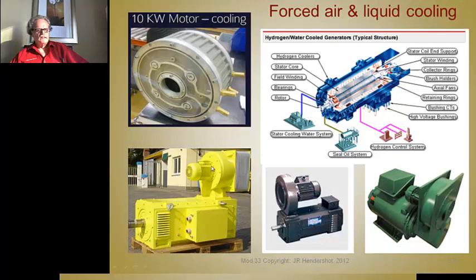Now here's a case of a big high torque density machine with an external blower on it that I don't know if that's blowing or sucking. I believe it's sucking because there's the filter system. You want to filter that air, so this sucks air in there and blows it through the machine, and it vents out both sides of the end bell, so that forces it out the end. The only thing about this, you have to keep this filter clean, so there has to be some kind of a temperature sensor or an airflow sensor, something in here that tells the controller or some maintenance people when the filters are dirty, because if those get blocked, you're going to cavitate and you won't get the proper cooling, and the motor will overheat.